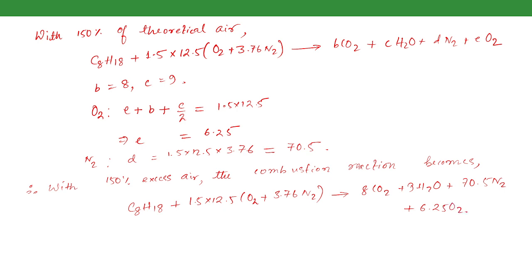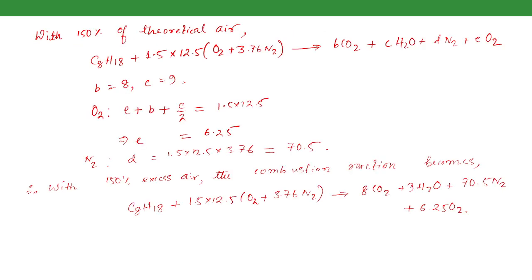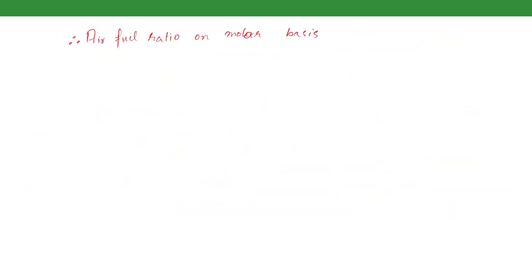Therefore, the air-fuel ratio on a molar basis is equal to 1.5 into 12.5 into (1 plus 3.76) by 1.